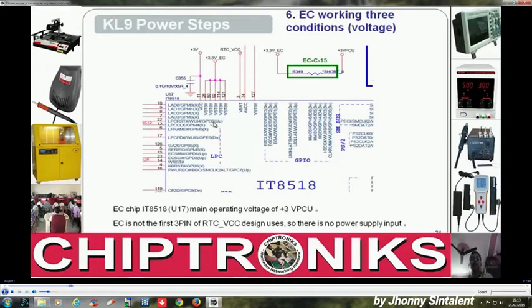What exactly are power planes? There are various power planes present in a notebook motherboard, right? So what are the important powers here for this IO controller? This 3.3 V underscore EC, the one connected to V standby, because this IO controller is turned on even when you do not press the power button.